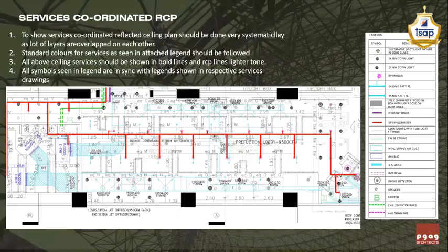the sprinkler risers and the hydrant risers are laid first, and then the HVAC services are executed. After the HVAC services happen, he does the conducting for all the electrical services and all fire alarm services. So that is the method which is followed for all the services execution.